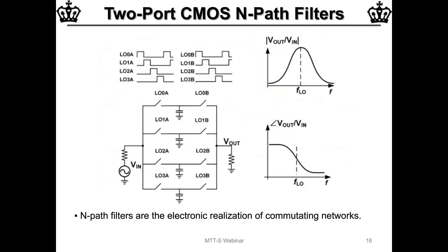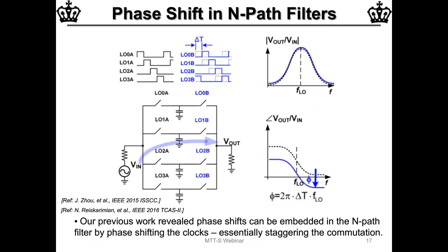So how this would be realized in an electronic circuit as opposed to that mechanical example is one would have these switches that are switching across some bank of 4 or more media. And in our first case, we actually used capacitors. So you imagine switches, capacitors, and switches, and these switches are being switched at an RF rate. But what we now have is that there's a phase shift of 90 degrees between the switches on the left and the switches on the right.